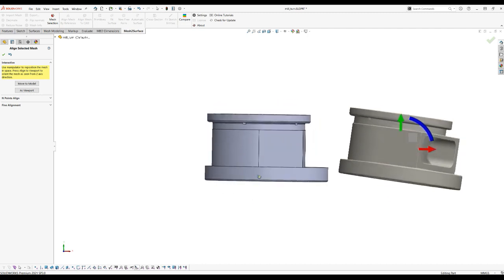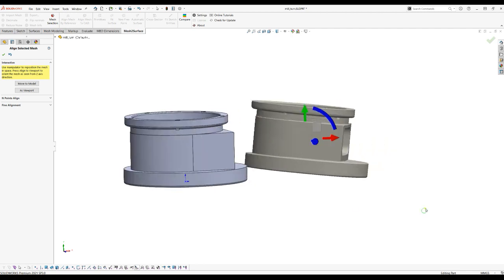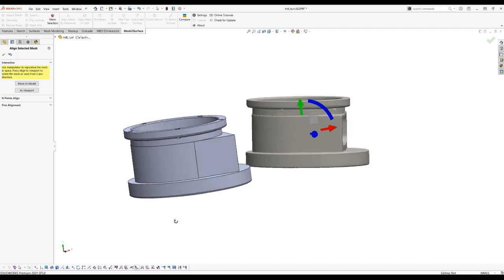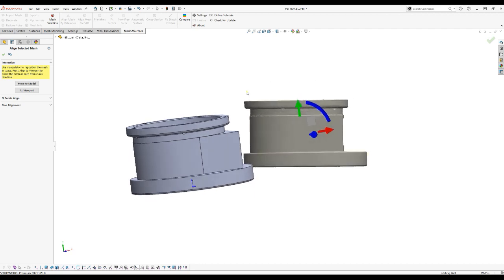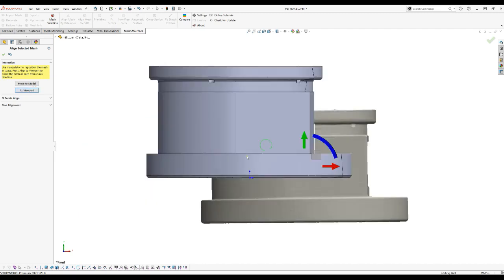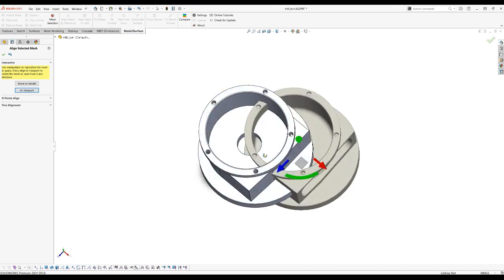Then, using the rotation button, I will adjust the view in a similar way so I can see roughly the actual scan data the same way as it looks from the Z direction from the front. When I adjust this, I can just place as a viewport. As you can see, the object has been aligned roughly into the same orientation.